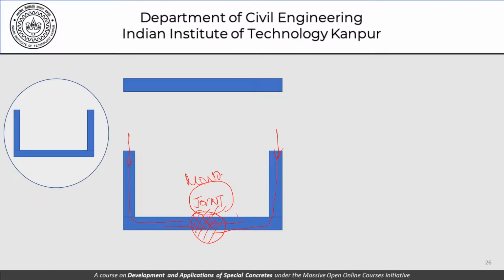Apart from that, we also need to ensure that we have formwork on the top, because after this concrete has been placed, this part has been filled up, we will expect the concrete to rise as far as these walls is concerned. So this will happen only when we have the top surface here having the formwork. So this is the other consideration, that while we are trying to introduce the concrete from the top, we have this issue that the concrete has to flow through a long distance through this bend here, and we need a formwork on the top. If we want to avoid this, and that will happen depending on what is the kind of actual width involved, what is the kind of distance that the concrete is expected to flow and so on,